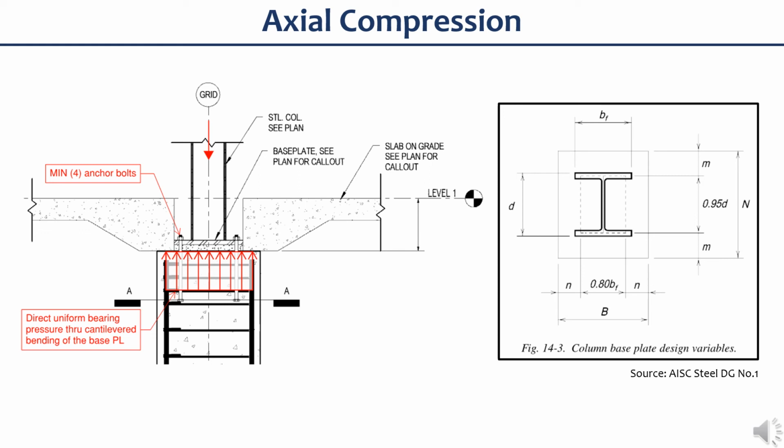But for column bases, part of special moment frames, it must have adequate strength to permit the expected ductile behavior for which the system is designed in order for the anticipated performance to be achieved. Now, column bases in special moment frame are required to be designed for the same forces as those required for the members and the connections framing into them. If the connections of the system are required to be designed for the amplified seismic loads or the loads based on member strengths, then the connection of the column base must also be designed for those loads.